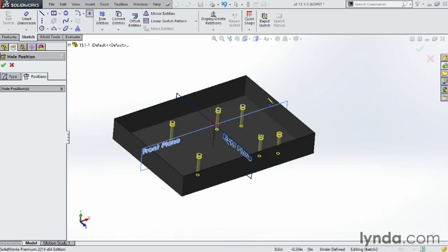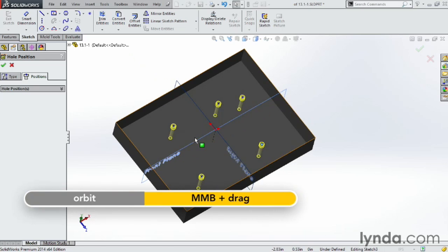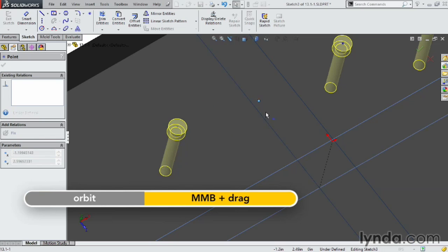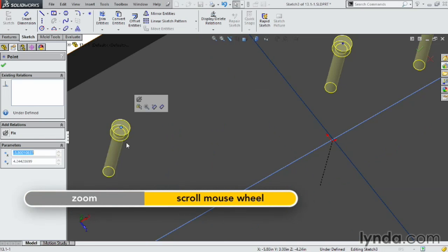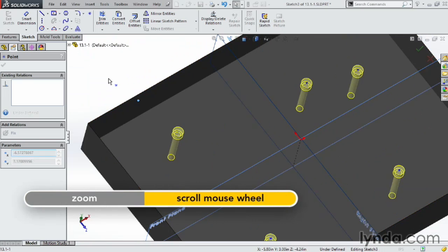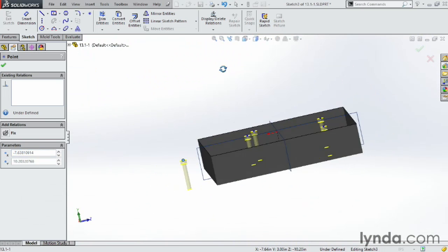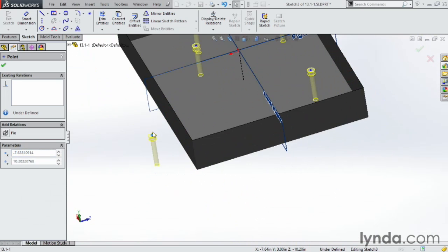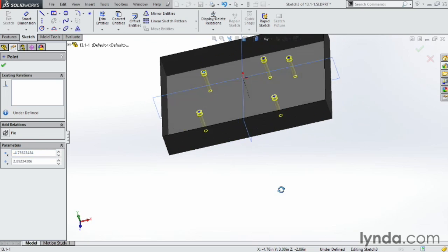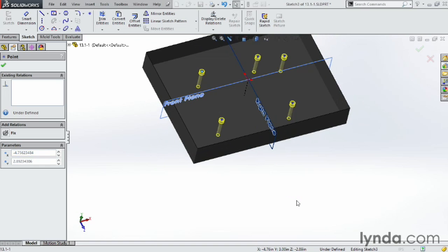Anywhere SolidWorks sees a point, it's going to put that same hole. Now if I want to turn off placing holes, I go up here and turn off the point command, or hit escape. Notice if I spin this around, these are just points. I can grab the point, and I can move it around anywhere on the screen, or anywhere on that face. In fact, I can even move it off of that face, although that's really not going to help us out, but it is possible to do that. It'll probably give you an error, but anywhere on that face, you can place those holes, and that's where it's going to be putting those holes. We're going to go over laying these holes out in the next couple of videos. But at this point, I just want to go through the main steps for using the Hole Wizard and getting the holes into the part.